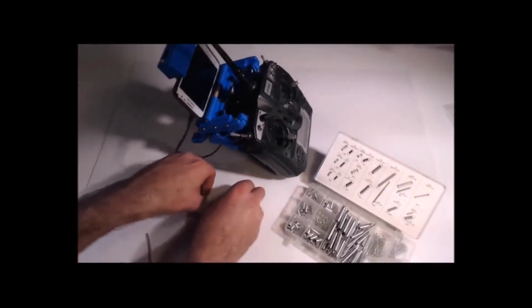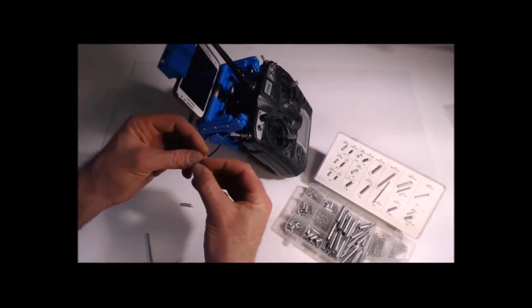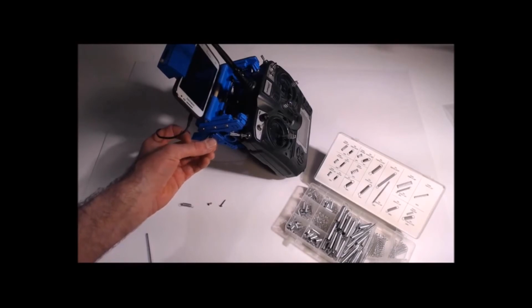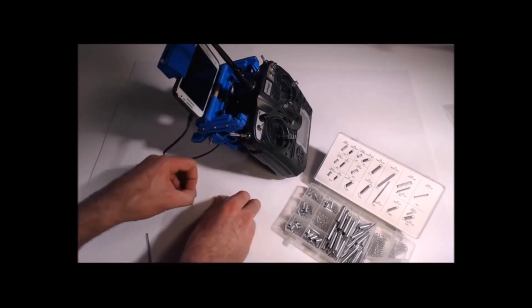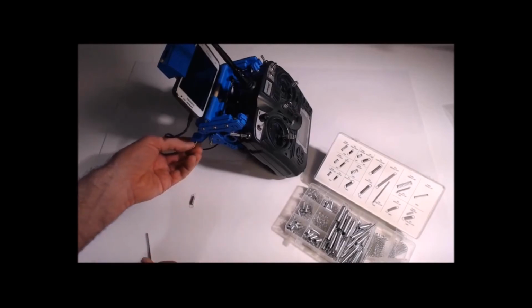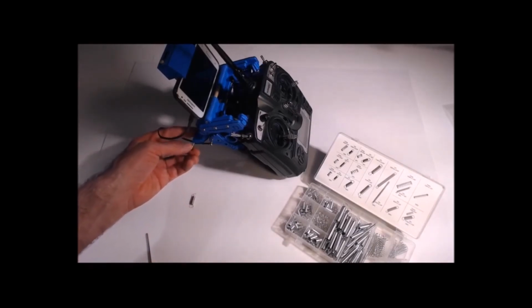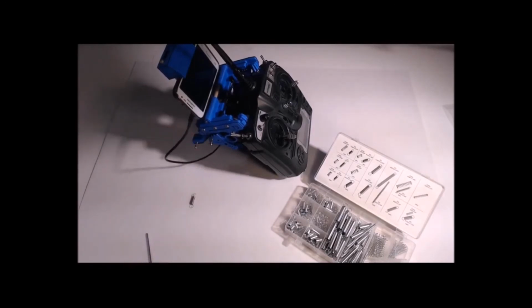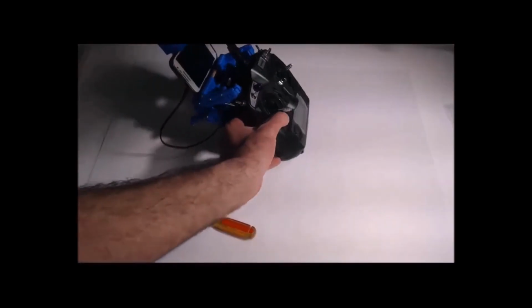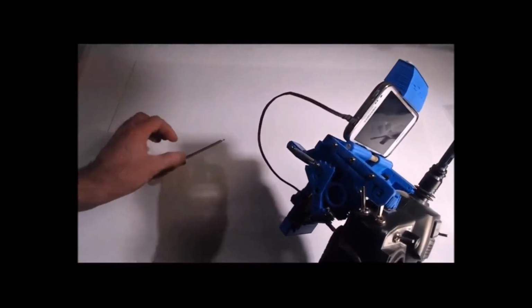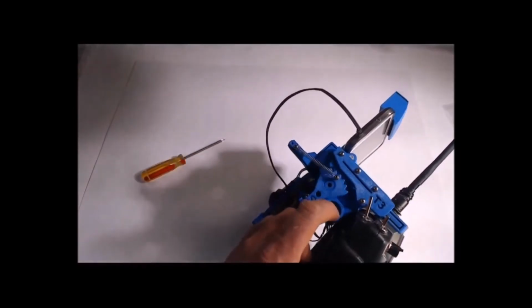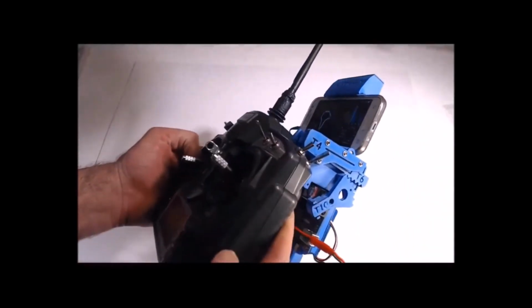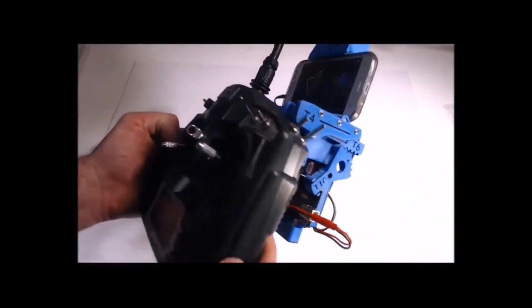So we're going to put these servo screws through the brass fitting and put one right there. This is on the manual side, the left side. And then one in this back one. I just put it in the middle one. There's actual adjustments in case you get a different spring or something. So I'll put that in real quick. Use a bigger Phillips on these servo screws. So now see that it's spring loaded. And this side, it's just like that.